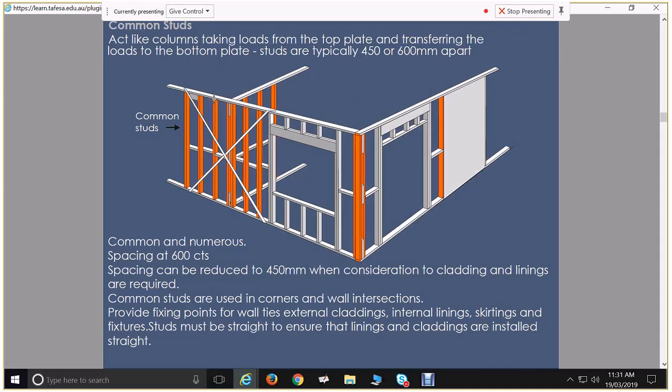Those bottom plates are tied down to our slab with masonry fixings like Dynabolts or Chemset anchors or blue tips, which are these self-tapping masonry screws. So those bottom plates are tied down to our slab, and our slab can't be picked up off the ground. It's quite heavy, it's sort of on the ground. Or with our suspended timber floor, we have concrete, or we have some form of tile happening there.